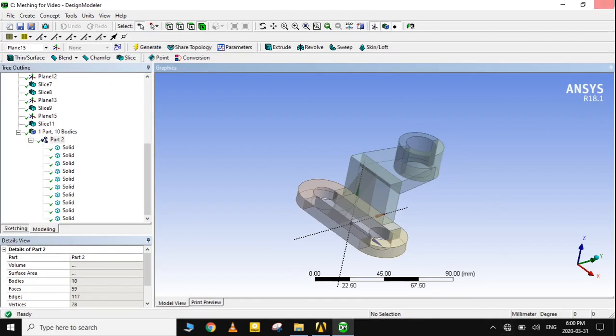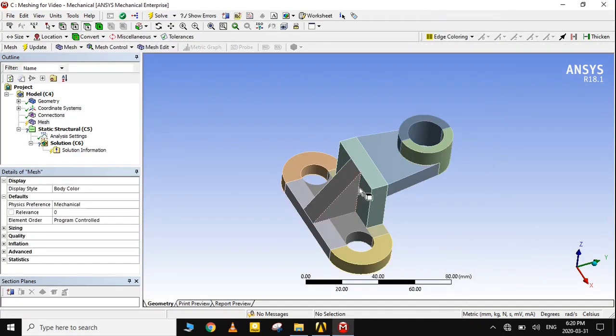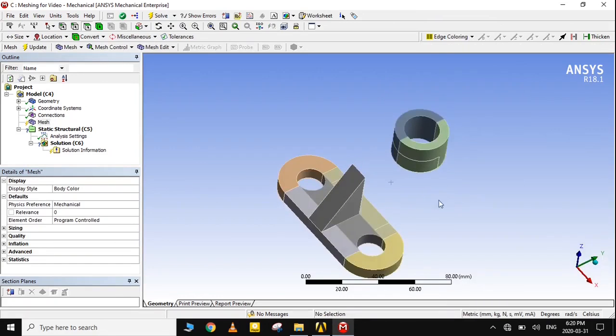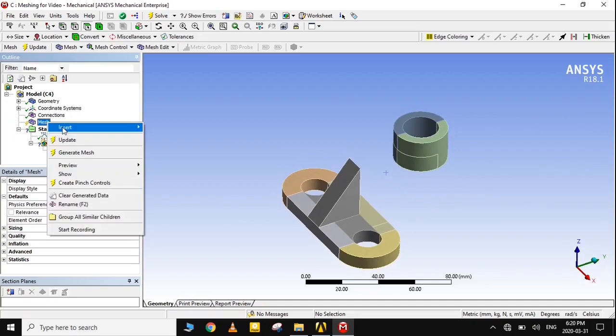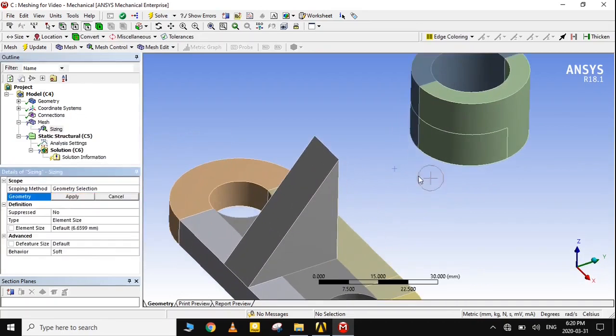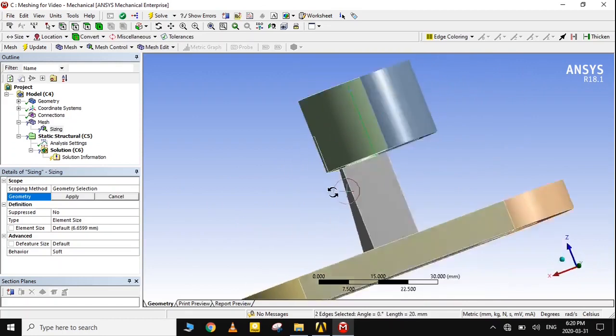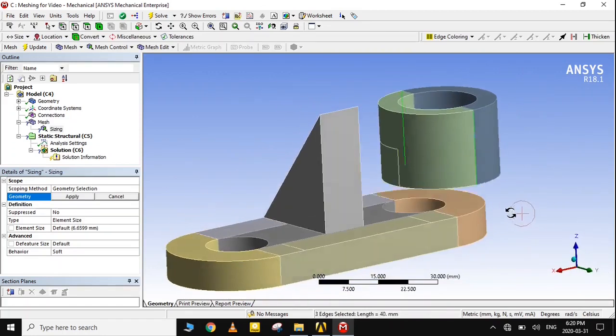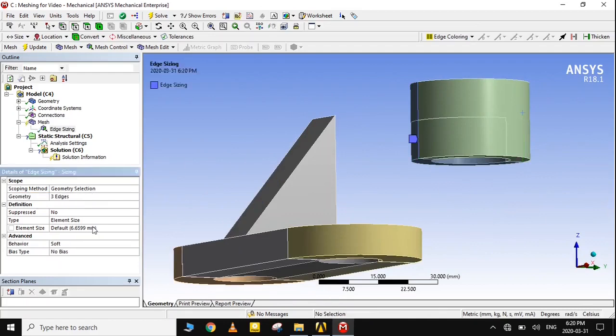Now, on to meshing. Our strategy is to obtain structured mesh one by one in different bodies. Easiest way to do this is to suppress the neighboring bodies and give the required sizing conditions to the one under consideration. The edges so formed by splitting the body will be used to control the dimensions of mesh elements in different regions. Give same element size or number of elements to edges through which you want the same family of lines to pass. Otherwise, we will not get structured mesh.